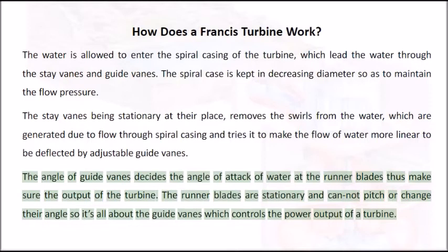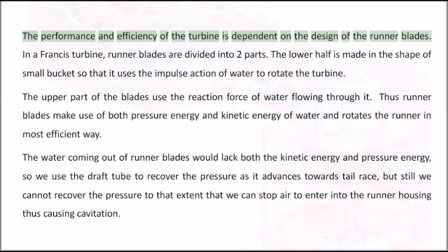The runner blades are stationary and cannot pitch or change their angles, so it's all about the guide vanes, which control the power output of a turbine. The performance and efficiency of the turbine is dependent on the design of the runner blades.